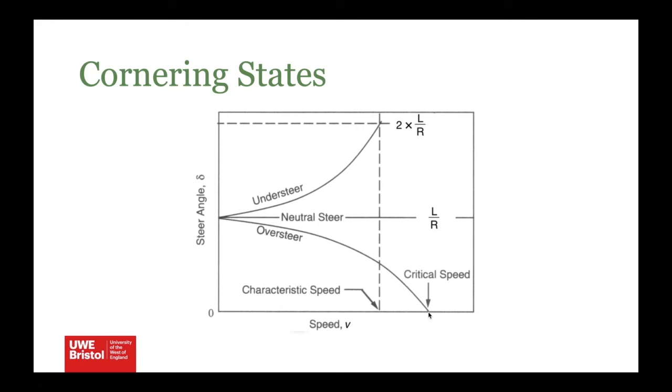If you want a car to oversteer, like for cameras or for drifting competitions, then you have to go beyond the critical speed, and you're applying steering lock in the opposite direction to maintain the corner radius. But often those situations aren't particularly steady state, so some of the behaviours are slightly different. But essentially, that's what's going on. So that's the situation.